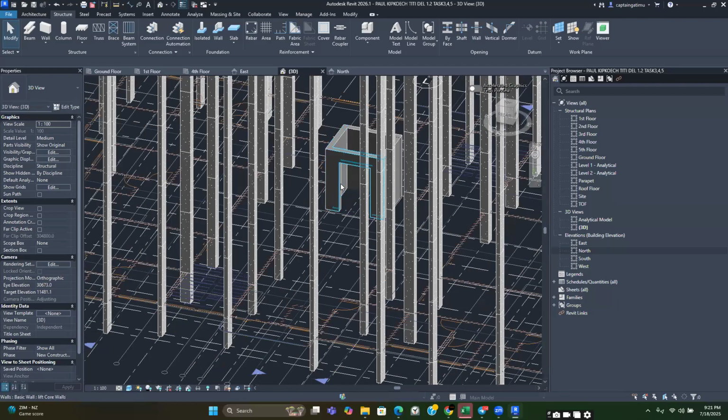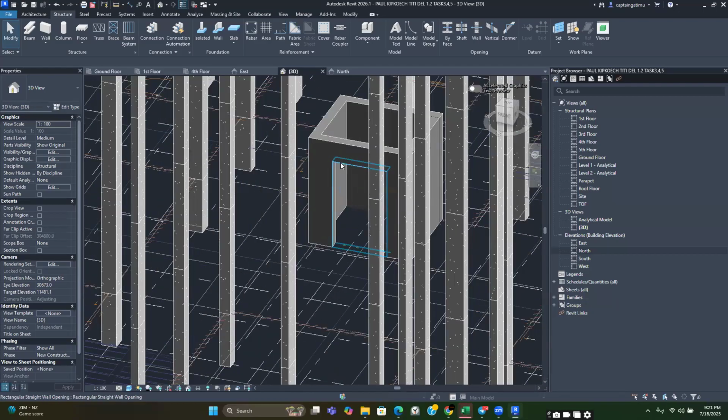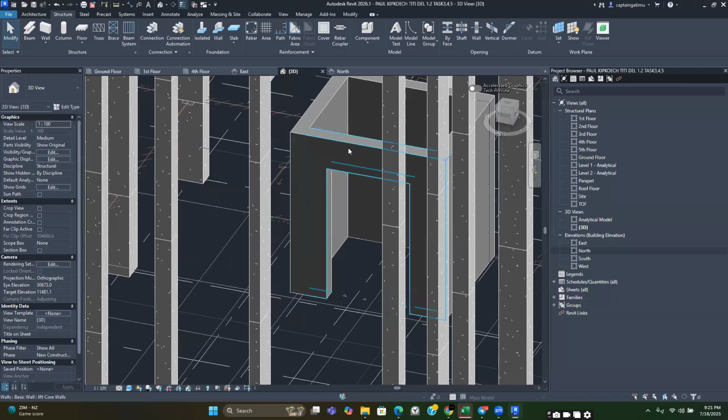Okay, so what I want you to do is I wanted us to look at this level here. This thickness above the opening, this is a structural member, and it is also going to be used to support our slab. So as we design or during your design phase, you are going to be able to determine this thickness and also the amount of reinforcement required.